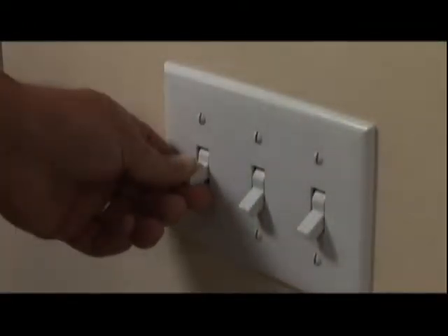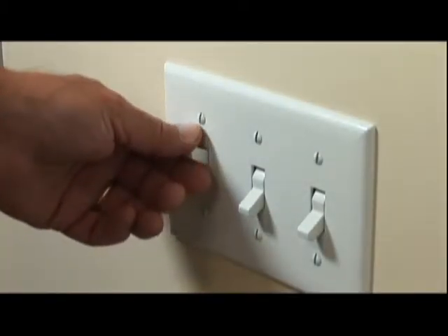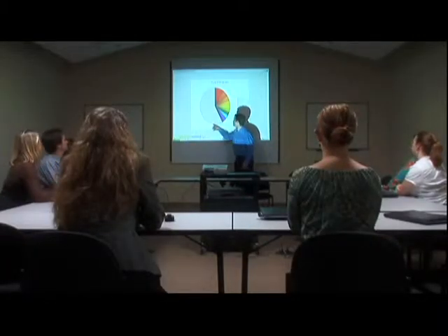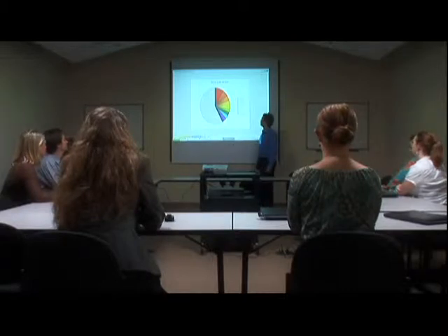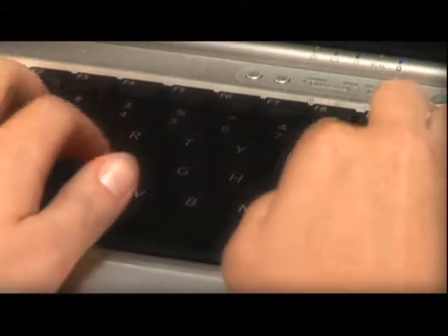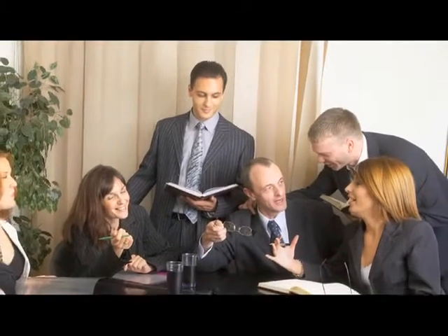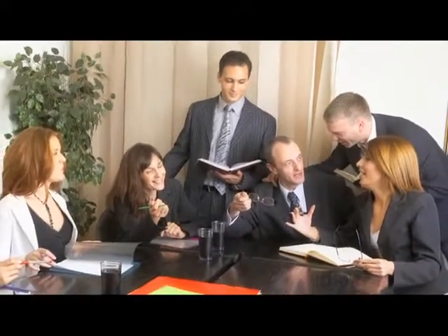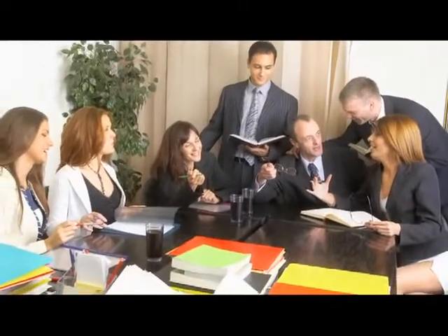Other controls include the use of shades and external window treatments when there is too much light, and either manual or automatic electric light controls when there's not enough. To adapt the amount of light in a space, for example to black out a room for a presentation, electric controls are used to either block out any incoming light or to augment the normal amount of light. To control shifting patterns of daylight, the contrast ratio between the task area and the surrounding space must remain constant, even as the absolute level of illumination changes. If the walls of the space are well lit and there's always an adequate amount of task lighting, the occupant will perceive the space as a whole to be lit in a comfortable way.